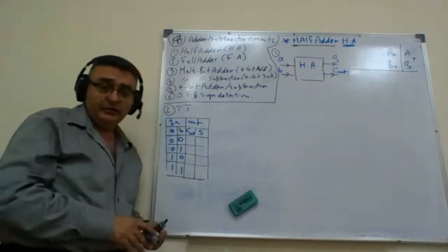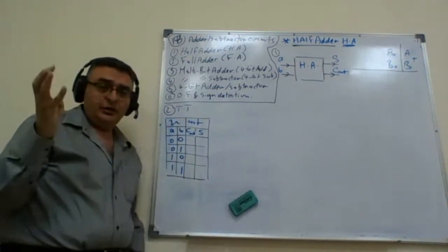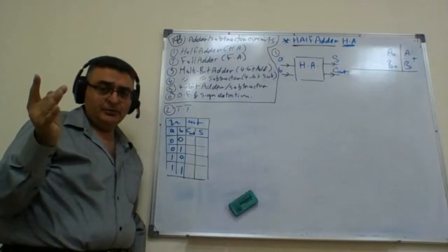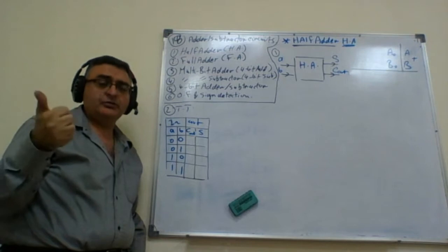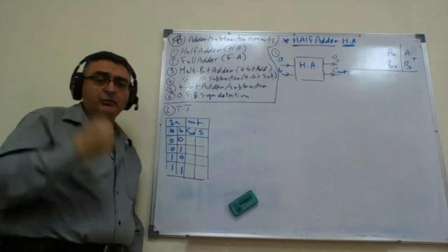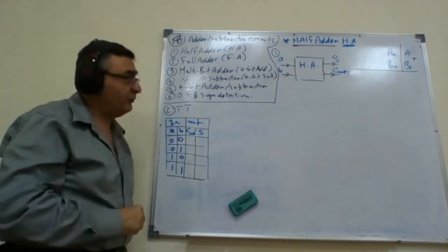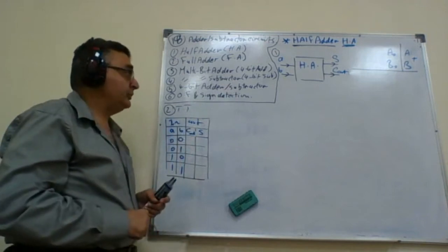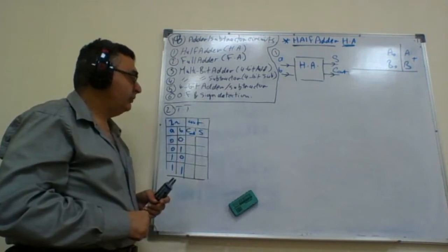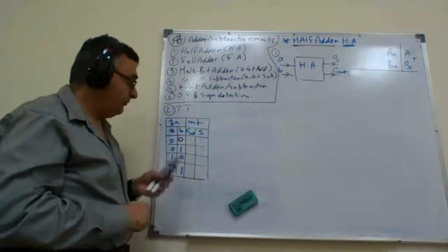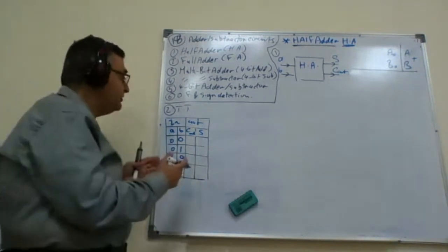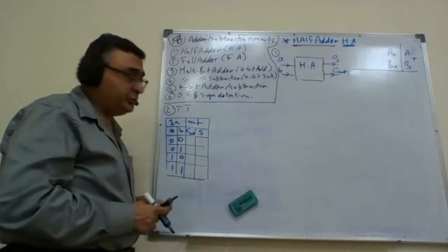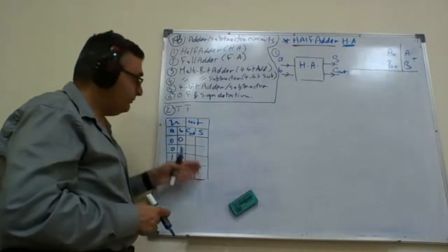We have how many steps? Input definitions, TT, K-maps, equations, and the circuit diagram. We have 5 steps to perform. We get the block diagram, we have our circuit here. Now can I fill in the TT? Yes. This circuit should add A to B and give me the output.